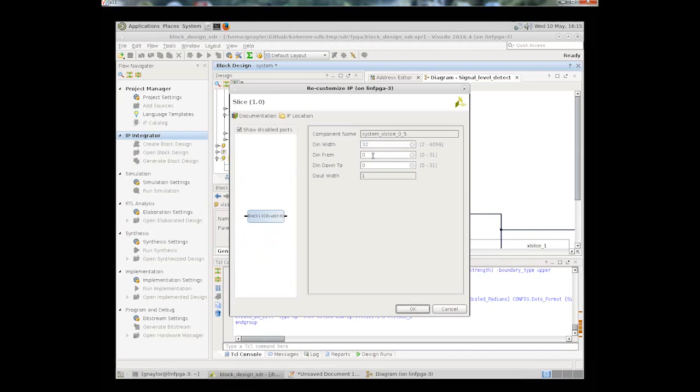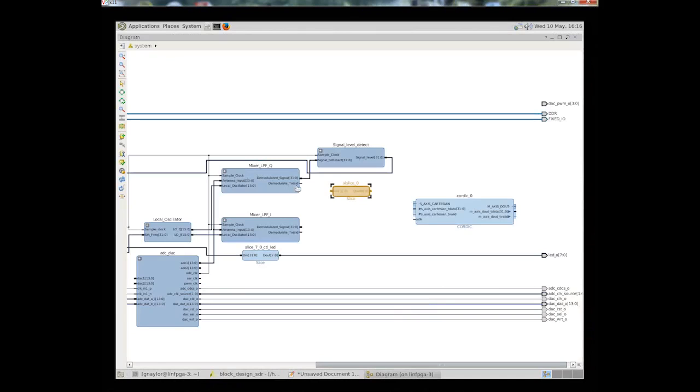So, hey, I don't know which 16 bits to take. We've got this huge dynamic range of the input coming out of these demodulators, and depending on the signal level from the antenna, our useful data could be anywhere in that huge dynamic range.